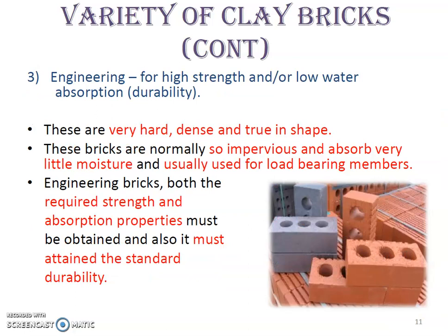Then we have engineering clay bricks, which have high strength and also low water absorption, which gives durability. Engineering clay bricks are very hard, dense and also true in shape. These bricks are normally impervious and absorb very little moisture, and are usually used for load-bearing members.